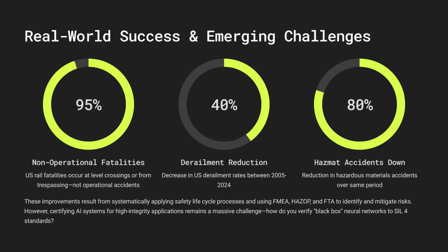And safety isn't just about the trains running on the main line, is it? The depots, the maintenance areas? Huge risk areas, especially with automated trains moving around without drivers. Dubai uses sophisticated depot personnel protection systems, DPPS, like the one from Zone Green. How does that work? It uses things like physical derailers, locked points, and complex electronic interlocking, all tied to worker logon systems. When a maintenance crew needs to work on a specific section of track in the depot, they log in, and the DPPS physically prevents any train from being routed into that zone and ensures the traction power is isolated. It's about physical and administrative controls protecting human life where people interact closely with automated systems.